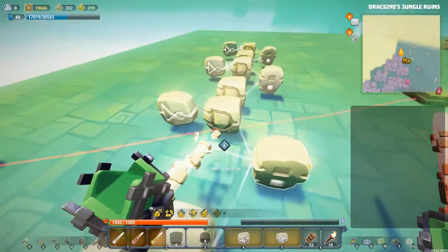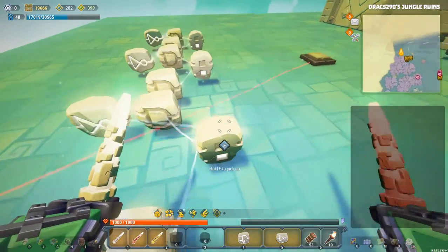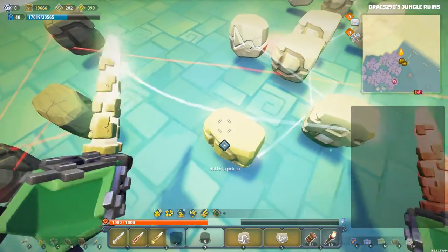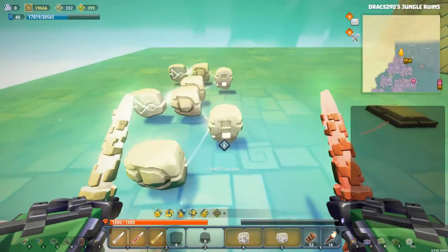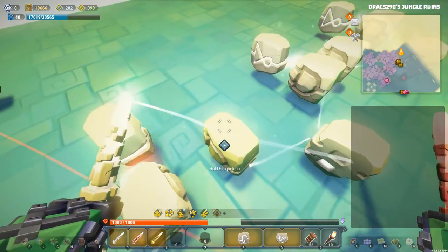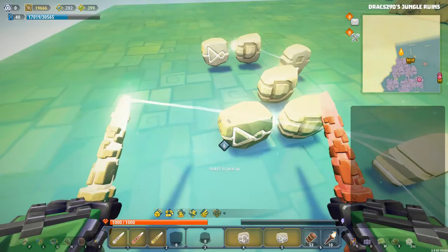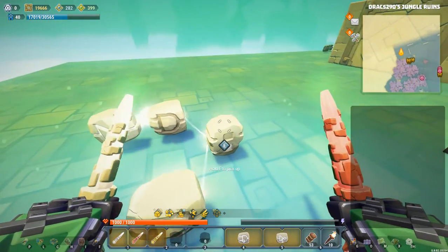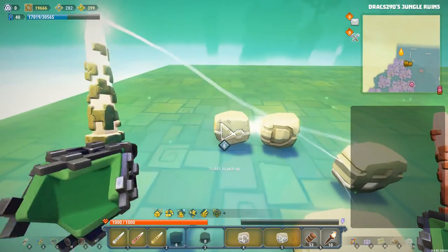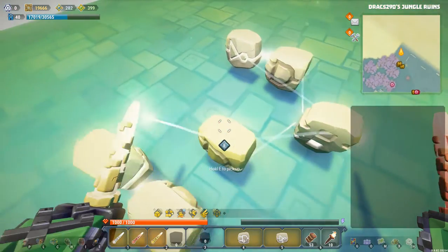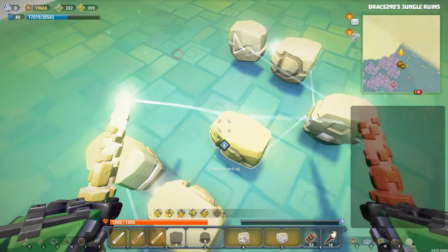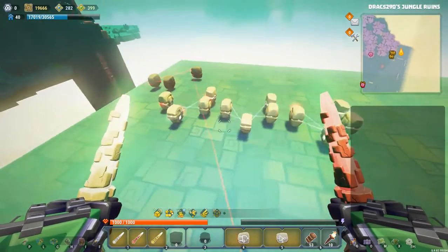Now the latch gets hooked to the NOT gate and to the A side of the other AND gate. And this is just all the way down. So we're going to do this the same on this side, once to the A side of this AND gate and once to the NOT gate over here. And then we're going to go again, so once to the NOT gate out the back and once to the A side over here. Right, so that's actually most of this circuit done and dusted.